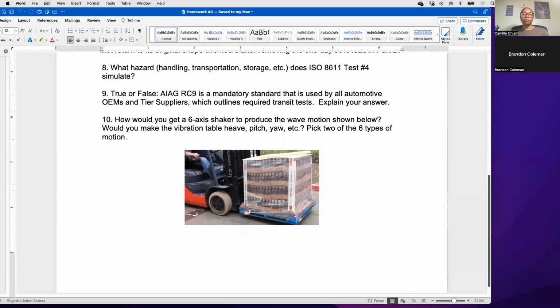You need something that's rugged, that can protect your heavy products, and definitely with the testing procedures it relates, because a lot of the testing I did back in the lab was for smaller products. So I did small drop tests and whatnot. But when it comes to industrial, we're using the vibe table, we're using forklifts, using more of the unitized pallet load test and ASTM. So I'd say it relates a lot.